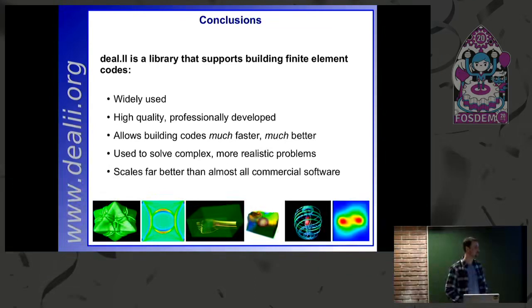Yes, a question on the grid generation side. You showed a complex geometry such as an aneurysm, for example. How do you typically do the grid generation? So how do we do the grid generation for complex geometries? We interface with tools like Gmsh, for example. We can read essentially every mesh format you can think about. So if your geometry is fixed, you take your CAD, you put it into Gmsh. Gmsh gives you a mesh. We take the mesh, and we solve on it.